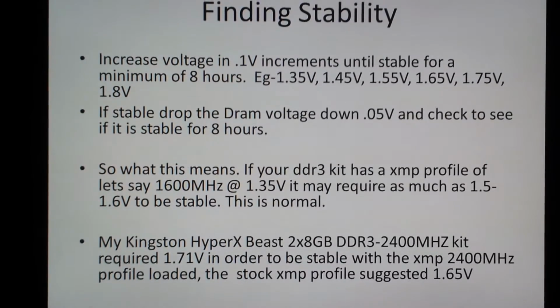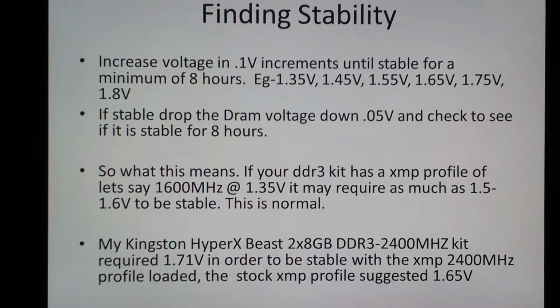So finding stability, here's what I'm going to suggest. We've set all of our parameters to auto. Now, if you weren't able to stress test and run for 8 or more hours, this is where this part of the guide comes in. We're going to start increasing the voltage in 0.1 volt increments until stable for a minimum of 8 hours. Once again, 8 hours is the magic number.